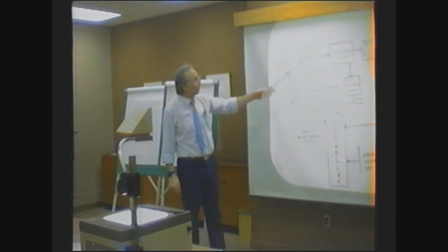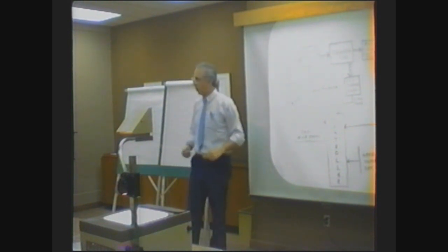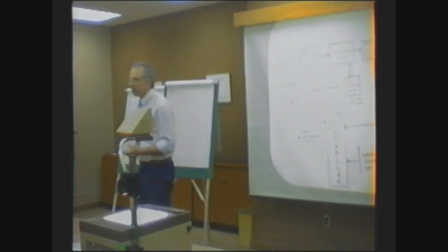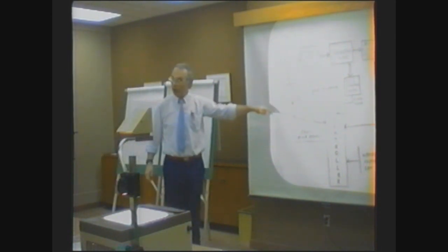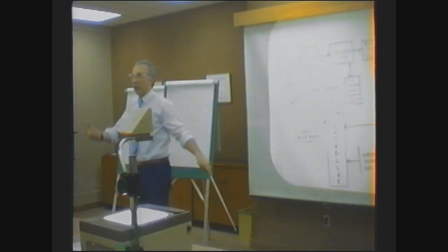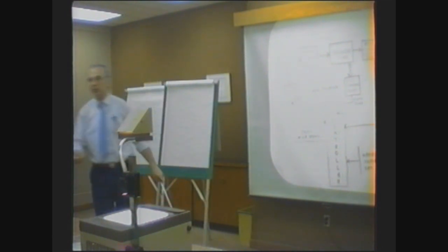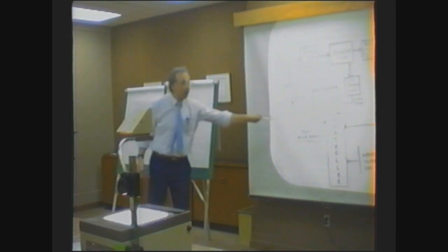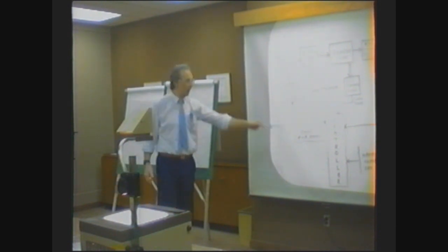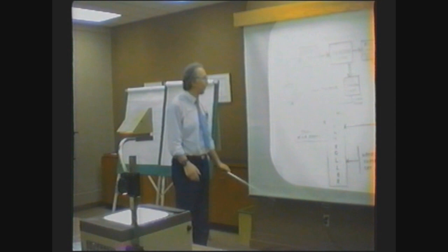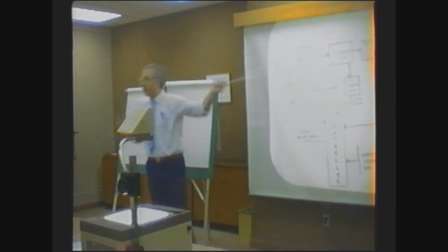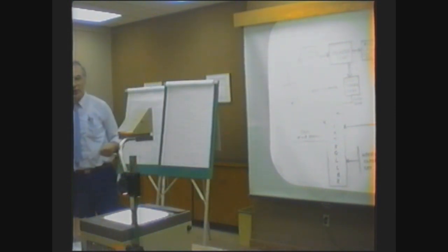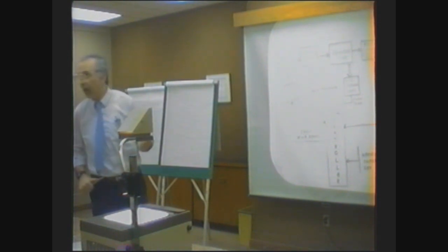Okay, but what happens? We want feedback from the control rods, which means we send something to the control rods, but the feedback is: what is the status of the control rods? They are available, they are unavailable, there is a problem. They moved the number of steps we told them, yes or no. All this comes back again to the programming controller as an input for our algorithm. So now, if you keep this figure in your mind, we're going to explain what the algorithm really does.